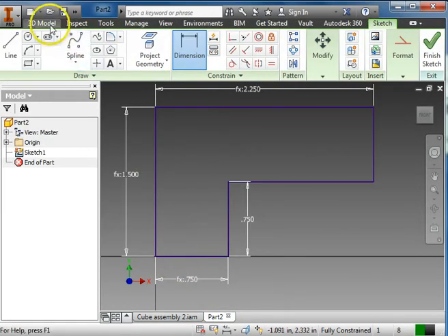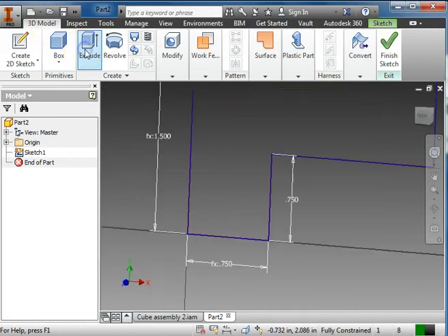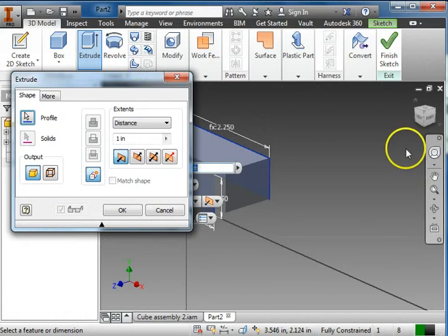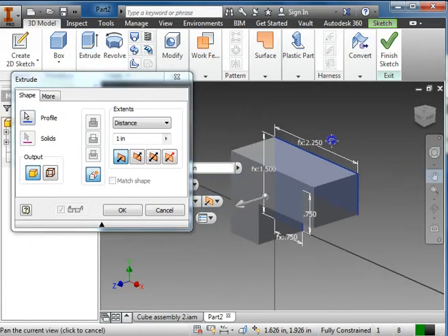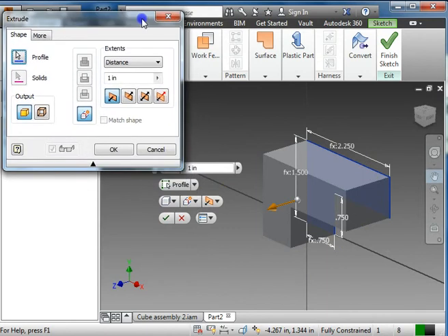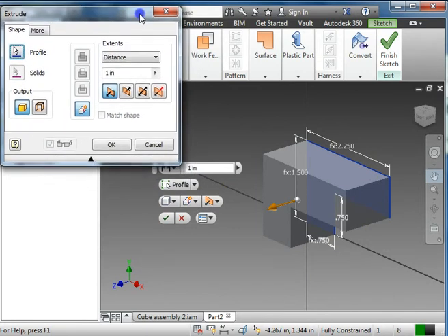So I'm going to click on 3D Model, Extrude, and since I've started the process of getting parametric dimensioning, the parametric dimensions are already here. And what I can do is tell this measurement to change and be this, D0. Let me move this out of the way just a little bit.